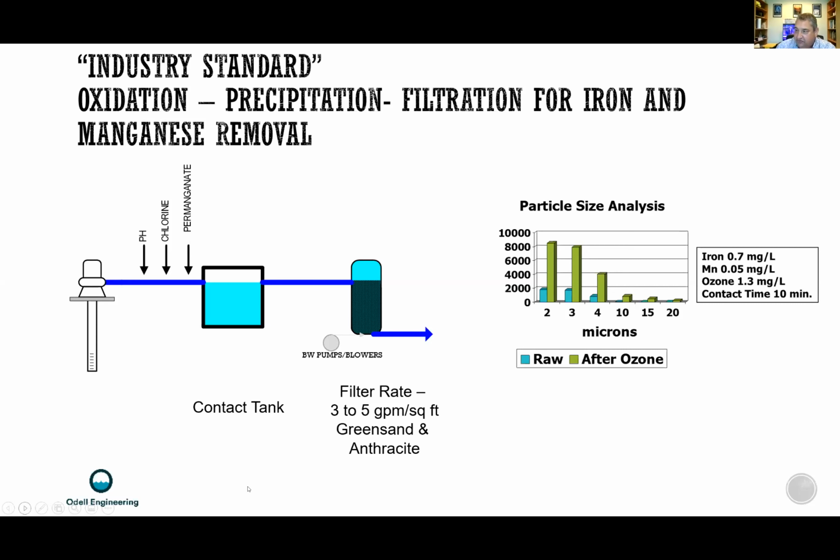That includes an oxidant addition, some contact time with maybe some pH adjustment, followed by a filter system that might include sand and anthracite, or green sand and anthracite.